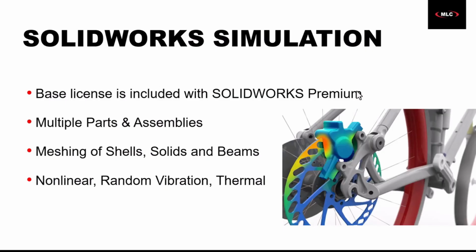We have more control over our mesh, which if you guys have any experience in simulation, you know that's absolutely crucial. The more mesh control we have, the easier it is to make sure we're not getting singularities in our stress, we're not getting inaccurate results, and we can actually make sure things solve faster and more accurately by using mesh types like solids and beams, or shells and beams I should say.